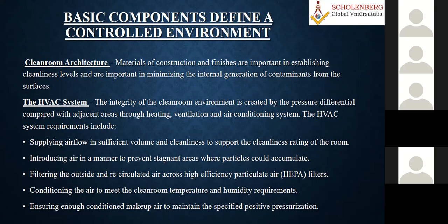And then you have to also consider your duct design in a manner to prevent stagnant areas where particles could accumulate in many places. Whatever you do, I am sure 100% nobody can eliminate it. But we can always try to minimize it by using improved design, improved format, so that whatever is the latest available, we should use it. And we should always prevent this type of stagnant area.